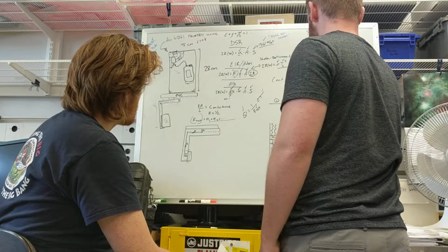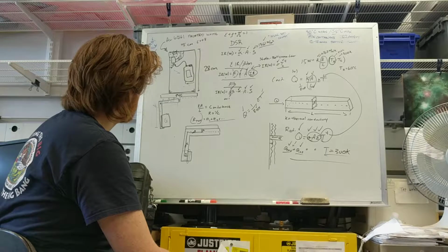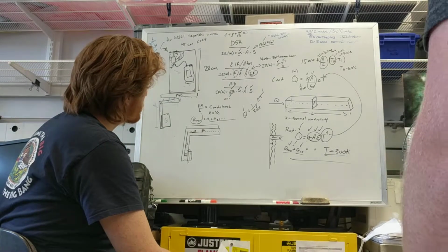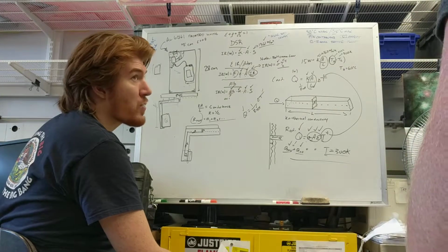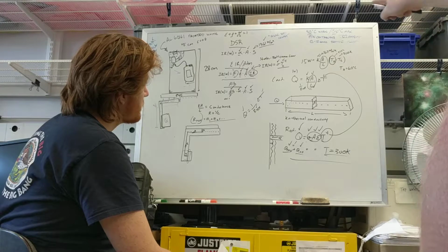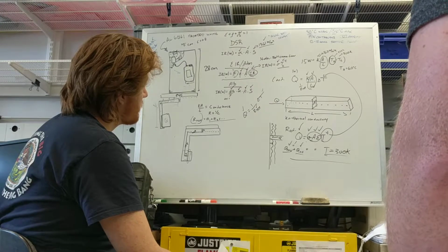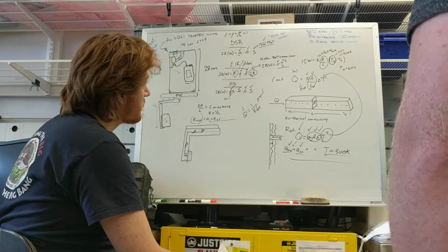This would probably take you 10 minutes to figure out what that T is. It's not a long process. That literally is a 10-minute or less calculation to find that T. And then that becomes your TL for your conduction analysis on what your thermal bar has to be, the bar where the heat transfers through, right?